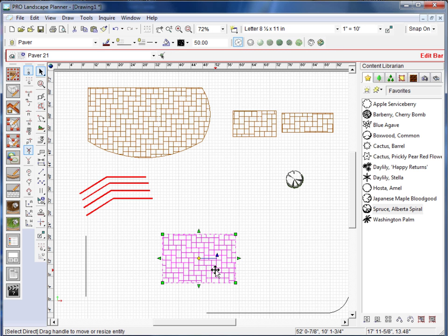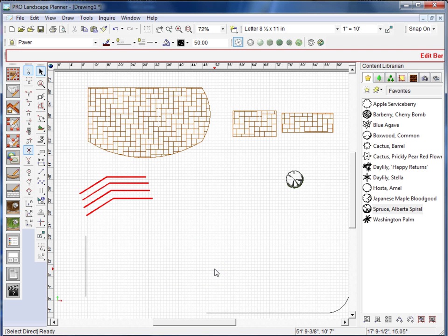Another important one is called the normal lock. Now a normal lock is easily demonstrated with the foundation wall tool. I'll select the foundation wall tool, and I'm going to unlock up here on the edit bar so that I can do a diagonal line. Now what I'll typically do is draw the longest wall that I have on a structure at the distance that I need here, at the angle that I want.